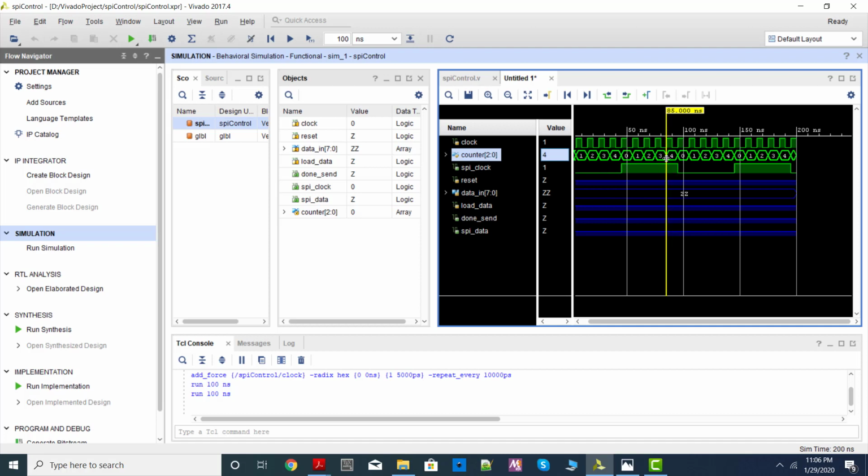So as far as this clock edge is concerned, the counter value is still 3. The counter value is 4 only here. That's why we compared with 4 instead of 5. Okay, so only if I write like this, I have 1, 2, 3, 4, 5 clock periods here and 5 clock periods here. So total 1 clock cycle here is same as 10 clock cycles here. That means this is 1 by 10th. So if it is 100 megahertz, this will be 10 megahertz.